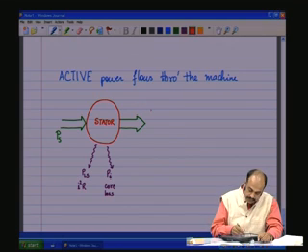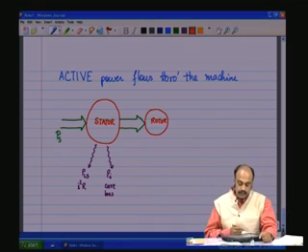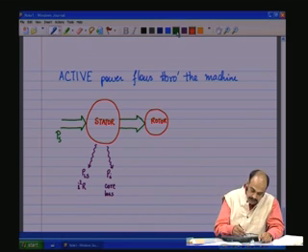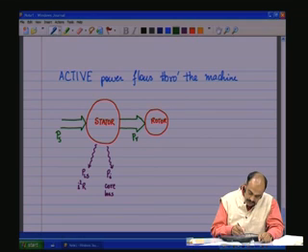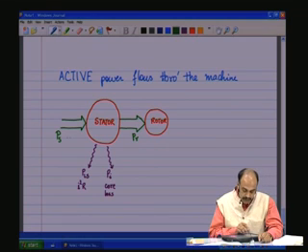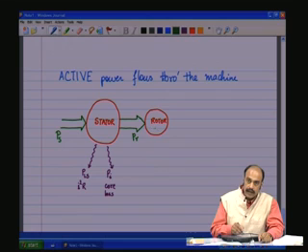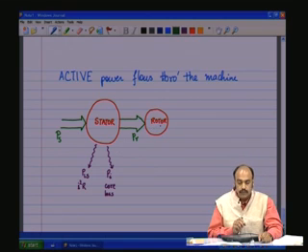The rotor input power we will call PR. So from the power input to the stator, PS, some amount goes off as I square R loss in the stator resistance and core loss, and the remaining power goes as PR into the rotor.